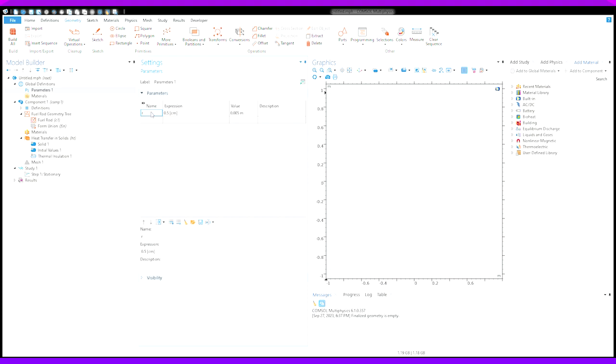But fundamentally, there have been a few exceptions, but we can input parameters in different units than our geometry tree's base unit. So say I wanted to do 50 centimeters instead for radius, it's the same thing. It'll do the conversion right there. So that's what it's reading in. So that's another thing the geometry unit does, it tells COMSOL what to convert these into as a baseline.